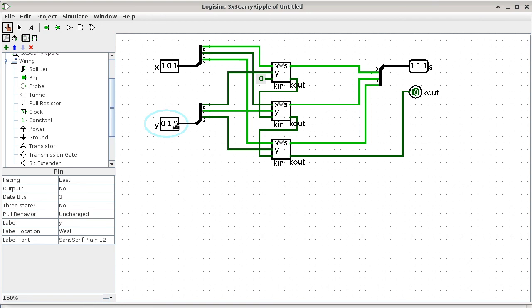If you figure out a 4-bit by 4-bit adder, it's going to take 2 nanoseconds to get all the results. Then a 64-bit adder is going to be 16 times that amount of time, because 16 times 4 is 64. So the wider the adder, the more time it will take to compute the result. So is that really a problem? It is not a problem unless your competitor has a faster way of doing it, right?